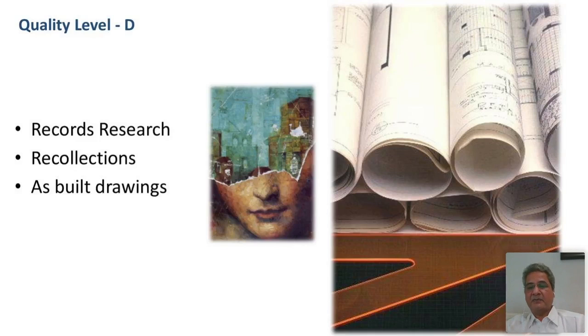He has been there in that shop. He joined that shop when he was a kid. Today he is grown up and he is still sitting there. He has seen practically all the excavation which has happened there. When a water pipeline was put, when a fiber optic cable was put, he knows that. He is a great source to tell you what kind of utilities you might find in a particular area.